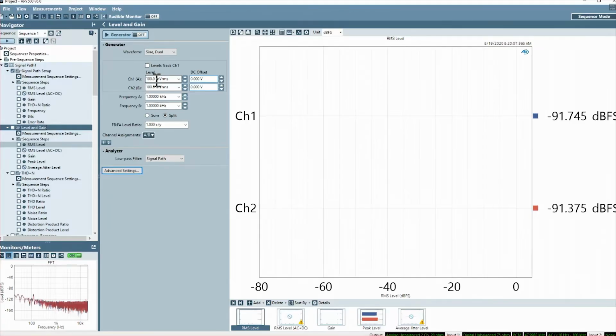All right. Next question. Is there a specific reason in the graphs that you use the stepped sine instead of a much faster chirp? Yeah, I think that's the question I answered previously, which is, depending on what frequencies you want to be able to sweep to and what measurement results you want to get, you sometimes just can't use a chirp.